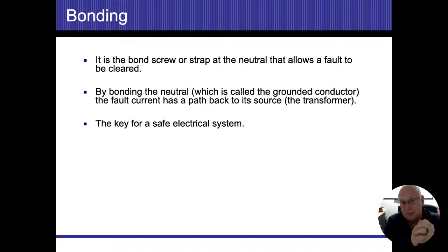If the GEC has insulation on it, then that should have a mechanical connection because we want to use the conduit as well that protects the GEC. We want to use the conduit as part of our grounding system. So we need to have a mechanical connection pretty much at both ends to the conduit. If it does not have insulation, so it's a bare conductor for the GEC, you will run into those, they are not required to have a mechanical or a metal connection at each end. So we don't have to tie it to the conduit. It makes sense because obviously if it's bare through and through, then most likely it's going to be touching that conduit in multiple places.